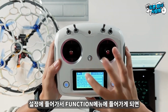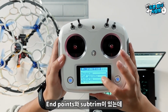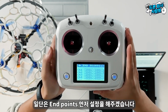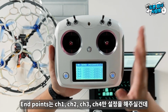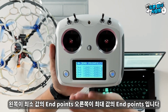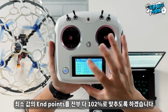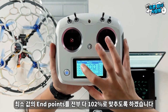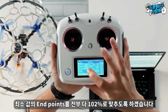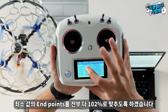When you go into the settings and enter the function menu, you'll find the endpoint and sub-trim. First, let's set the endpoint. You will only set the endpoints for channels 1, 2, 3, and 4. The left side is the minimum endpoint and the right side is the maximum endpoint. So let's set all these endpoints to 100%.